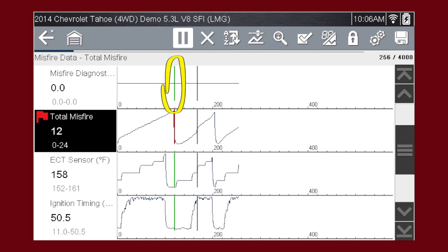A green cursor line is displayed on all the other PID graphs to indicate their relationship to where the trigger occurred. This allows you to see what was happening with the other PIDs at the time the triggered PID exceeded the min-max values. After a PID trigger has been activated, a short data recording is automatically saved. The gray line shows the point where the data was saved.